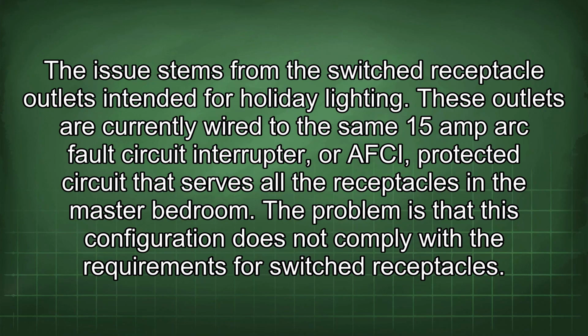The issue stems from the switched receptacle outlets intended for holiday lighting. These outlets are currently wired to the same 15 amp arc fault circuit interrupter, or AFCI, protected circuit that serves all the receptacles in the master bedroom. The problem is that this configuration does not comply with the requirements for switched receptacles.